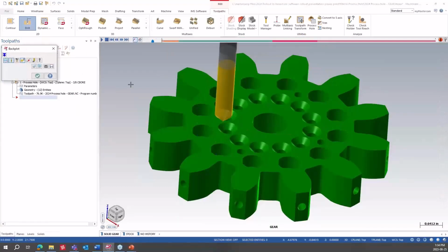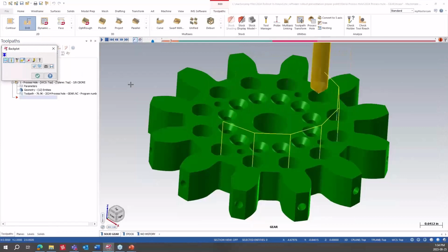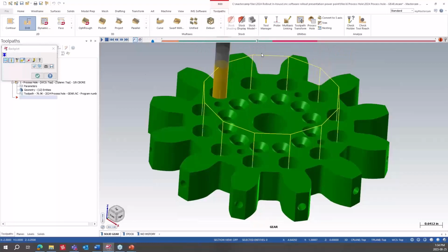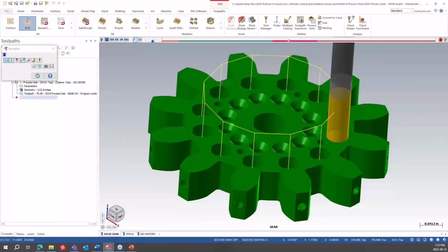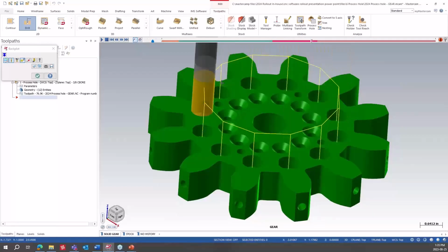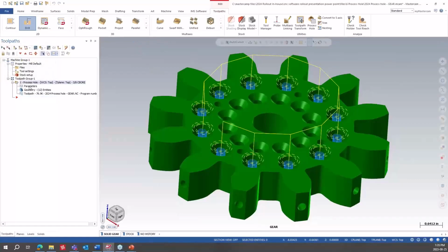One of the things that I did in mine, I center drilled and then drilled. I just wanted to do this to show you can have it as an option. Many shops, when you're doing stuff like a counterbore, I plunged the tool for the counterbore, but then I've also added a helix operation. This is good if you were working in a shop and, say, the counterbore size wasn't the tool that you had at that time. By building this into this library, you have options now to use whatever toolpath you want.